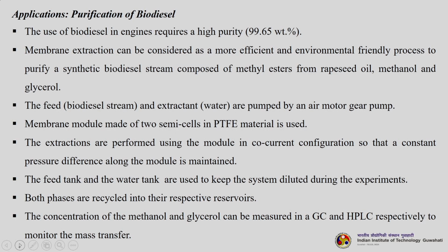Another application is purification of biodiesel. The use of biodiesel in engines requires a high purity, almost 99.65 weight percent. Membrane extraction can be considered a more efficient and environmentally friendly process to purify a synthetic biodiesel stream composed of methyl esters from rapeseed oil, methanol and glycerol. The feed biodiesel stream and extractant water are pumped by an air motor gear pump. A membrane module made up of two semi cells in PTFE material is used.